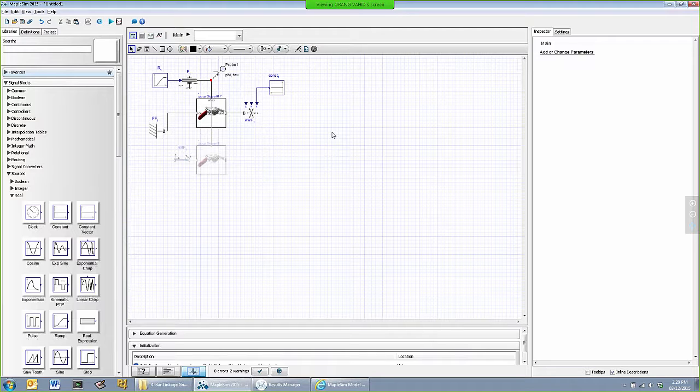The question would be, what is the effect of the external force? What is the size of the motor that I would need to be able to actuate this and make sure that the gripper applies a certain amount of force as it grips the objects, as an example that we are exploring today. So assuming the topic is what would be the torque requirement, given the inertial forces, the acceleration that the system sees, and also the requirement for the external force.